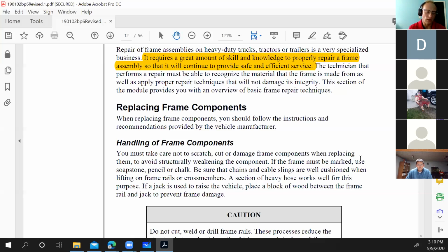And heat damage is tricky because you typically will need to bend it back and then reinforce it. A lot of times once it's heat damaged, you have to replace it or reinforce it. You can't just bend it back. Whereas something like a bend, if it was cold bent, you can bend it back and it should be okay as long as you're bending cold. Does that answer your question? Oh yeah, that's awesome.